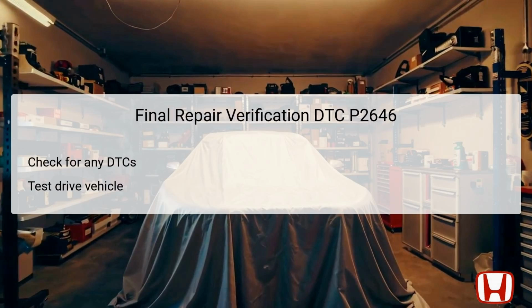After completing all necessary repairs related to DTC P2646, a final verification process is essential. Begin by scanning for any existing diagnostic trouble codes, DTCs, to ensure the system is functioning correctly. It's critical to ascertain that no new codes or prior codes have reappeared post-repair. Following this, a test drive of the vehicle is critical to validate the repair under actual operating conditions.